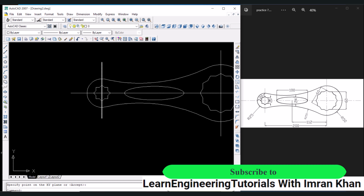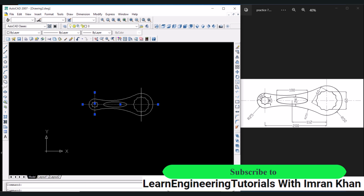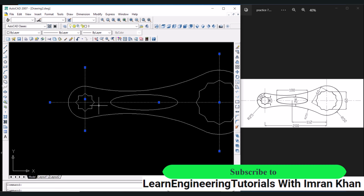Now we have to modify these lines, so click on these lines, and then in the property menu we can select the line type. So if we click over here, we can see by layer, by block, continuous and other.